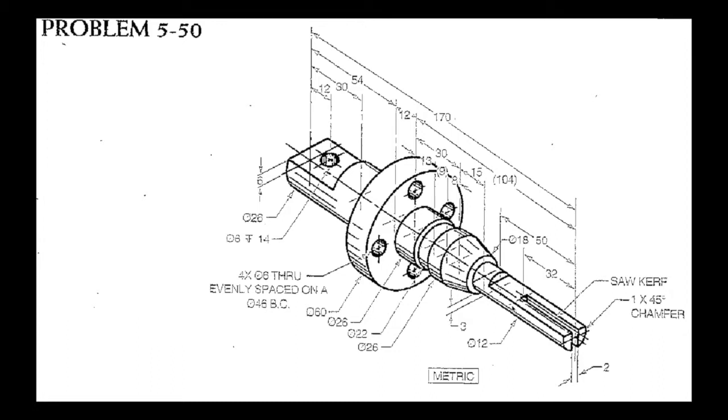This is obviously going around a 360. So I'm going to ignore these flat areas in the back and on the front, and the holes for now, and just make this cylindrical piece. To understand what we're looking at, if this is our front view looking at it from this direction, I'm going to think of the widths from left to right. Those dimensions are pretty obvious. However, the heights are given to me in diameters.